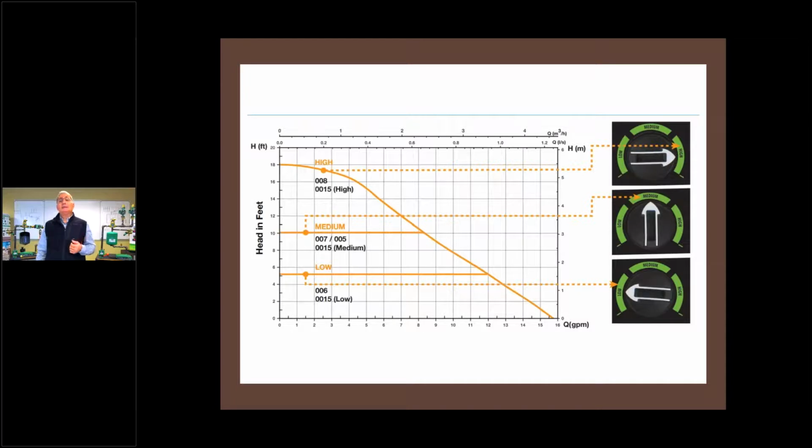And if we did hit our design conditions, our delta would get wider than we want. Would that be a bad thing for the condensing boiler? Not at all. Could that affect the comfort in their home? Possibly. So if you wanted to, you could run it there. And if they were complaining of not being comfortable if we hit a cold streak, all you got to do is put it up to medium speed. So now, if it was at medium speed, I would be plotted here.